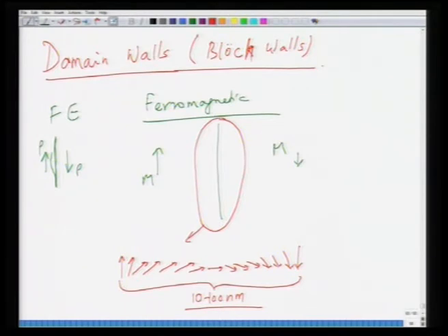In ferroelectric materials, we are talking of a domain wall size of a couple of lattice parameters, and a typical lattice parameter is somewhere around 4 to 5 angstrom. So this would be somewhere around 10 to 15 angstrom in ferroelectric material, whereas in ferromagnetic material it is like 1 nanometer upward, so we are talking about two orders of magnitude wider domain walls.